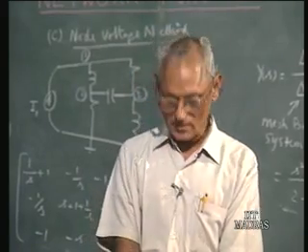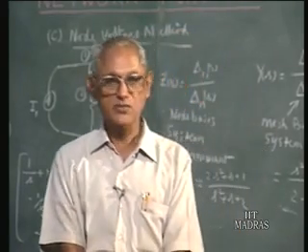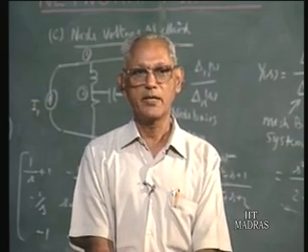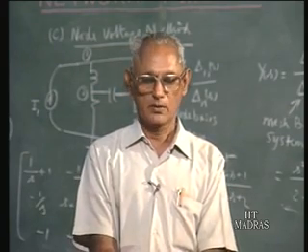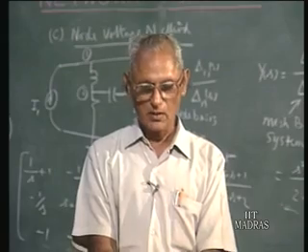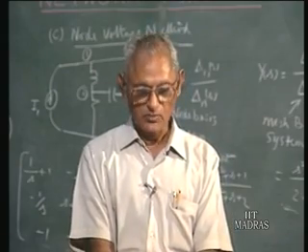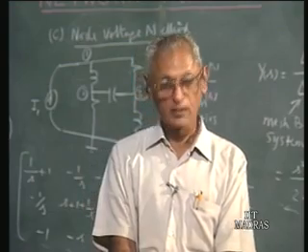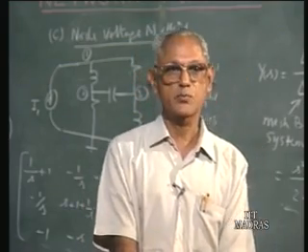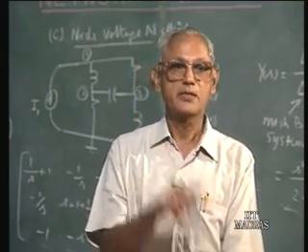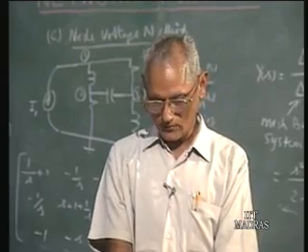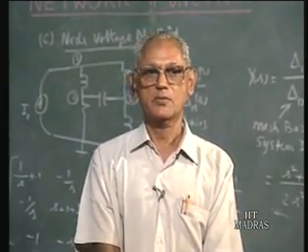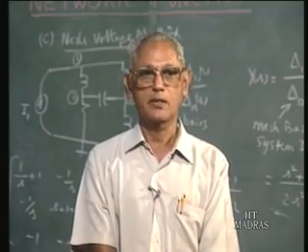We also mentioned that once we have the admittance function or impedance function known to us, we can find the response to any other excitation by taking the Laplace transform of the input, multiplying by the network function, finding the Laplace transform of the response, and taking the inverse Laplace transform. We can also use this to get the steady state response under sinusoidal conditions, by deriving the frequency response function from the given network function by substituting j omega for s and taking the appropriate value of omega.